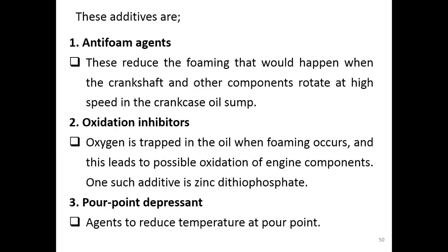The additives that we add into the lubrication oil are what? The first one is the anti-foam agent, or anti-foam additive. This additive is used to reduce the foaming that would happen when the crankshaft and other engine components move at high speed in the crankcase oil sump.